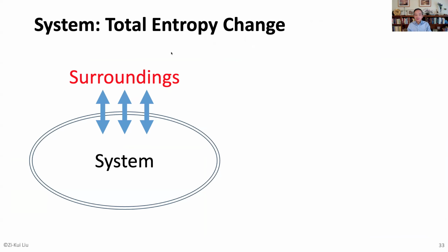Okay, so in this process we have to combine the first law and second law. So we have to think about entropy, right? Because of the entropy production. That means we have to first work out the total entropy change of a system with these three exchanges between the system and its surroundings. So it's heat. We know already that the heat change divided by T is equal to dS. So that's the entropy change of the system due to the heat exchange.